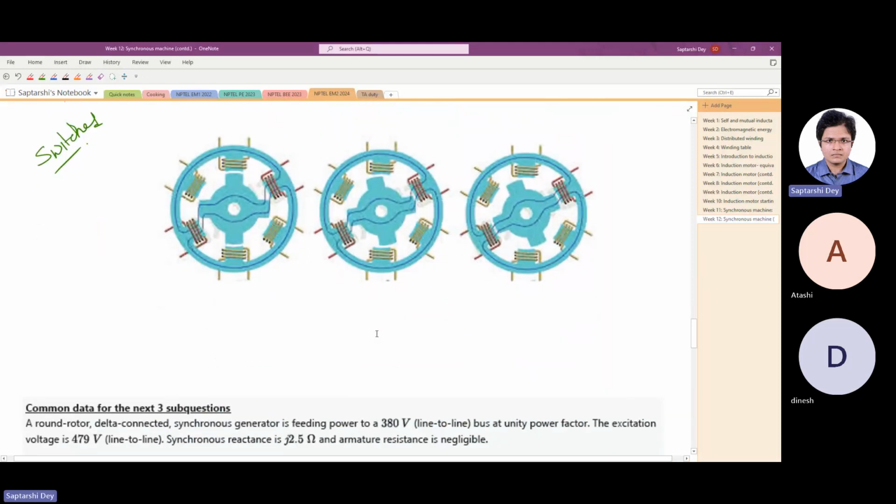Right? So it's like this. Suppose this rotor, so it's a double salient machine, probably the only double salient machine, or apparently double salient, as we saw that IPM is also salient, not double salient. This is the only double salient machine that you will see. I do not think there is any other. IPM is salient, but only on the rotor. So doubly salient, both the stator and the rotor are salient.